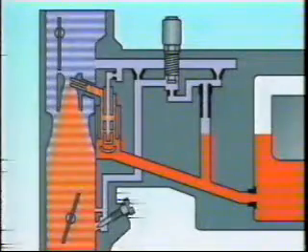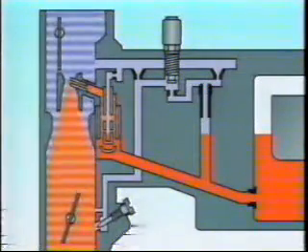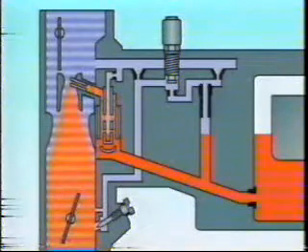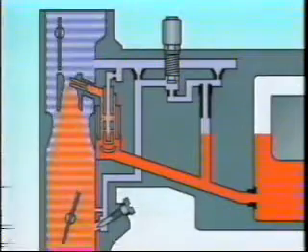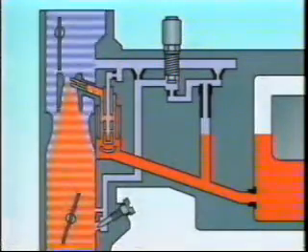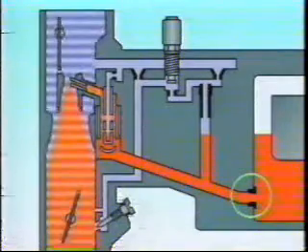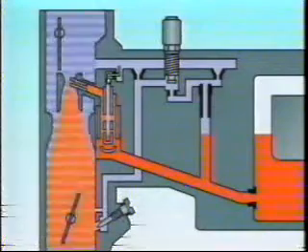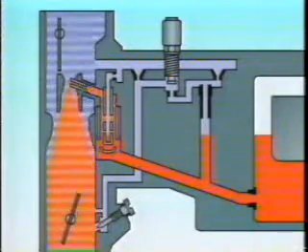The primary high-speed circuit works as follows. When the throttle valve is opened wide, allowing for a higher speed and volume of air to the Venturi, the amount of fuel that is delivered is equivalent to the intake air volume drawn into the barrel. The amount of fuel is controlled at the main jet before it is mixed with the primary air bleeder and injected from the main nozzle. The fuel is atomized by the air flowing at high speed past the Venturi, from which it enters the combustion chamber.